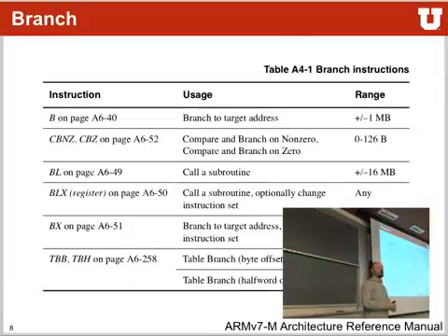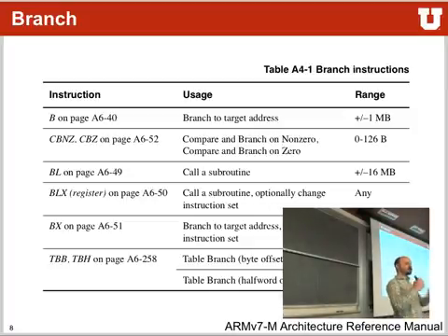We talked last time about the branch instruction, and this time I bring it up again because I want to look a little more at the encoding of these different things. We have the encoding of B that can jump plus minus 1 megabyte. We have other functions that can only go up to 128 bytes. Others go up to 16 megabytes, any kind of size, etc. We talked last time about why this is the case. B instructions can only go that far because they are encoded in 16 bits. Other instructions are encoded in larger numbers, and that way they can have larger constants associated to them. And those that can jump anywhere are usually based on a register, where the jump address is stored in a register and not encoded in the instruction itself.